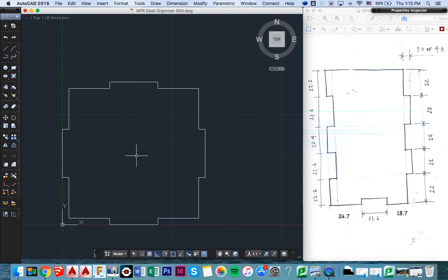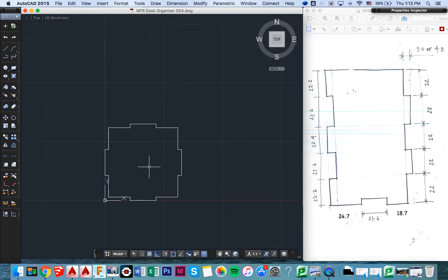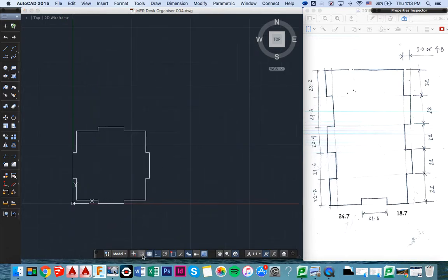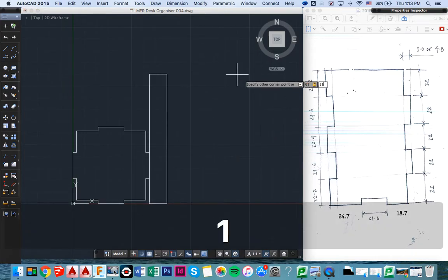So that's the base. How about we go Command S to save that now? We're just going to click on the grid for a minute. And we're going to draw our rectangle, the same as this one over here. So RECT again for rectangle. Snap it down there. The size of this is 65,110.